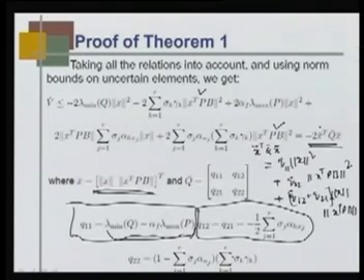So I hope you understood how we finally wrote v dot in terms of a quadratic function x bar transpose q bar x bar, and you saw that v dot can be, what is the advantage of this? If I can write v dot as x bar transpose q bar x bar, then if q bar is positive definite, since there is a negative sign here, v dot is negative definite, hence the system is stable.